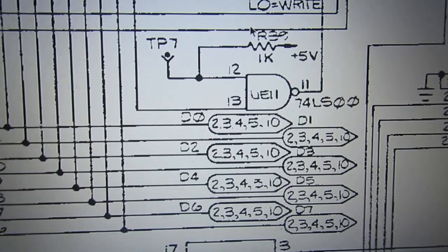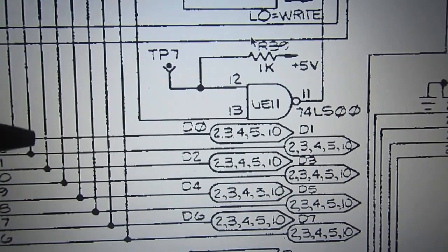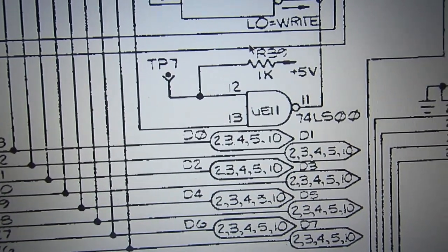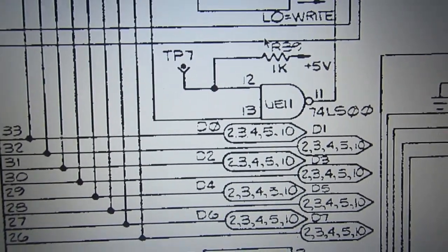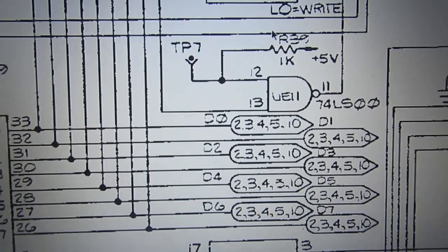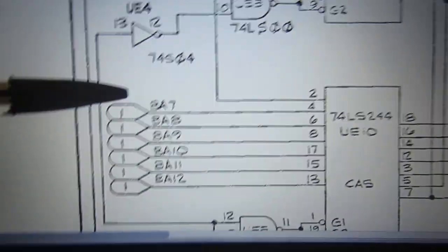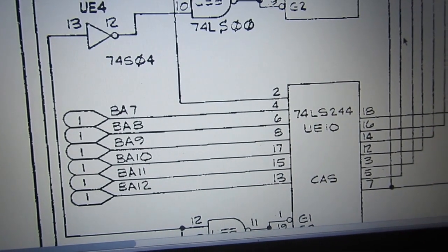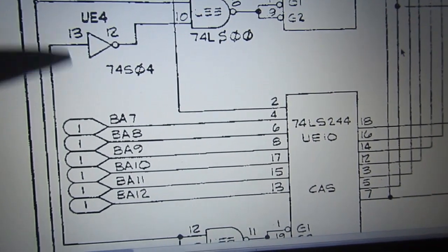So any suggestion from a test should be checked, and I really checked all the address bus lines before even running the test, and they were all fine, so I was sure the test was not correctly identifying the real problem. Actually, another thing that was misleading was the first part of the screen had all correct characters. That may be for a couple of reasons.